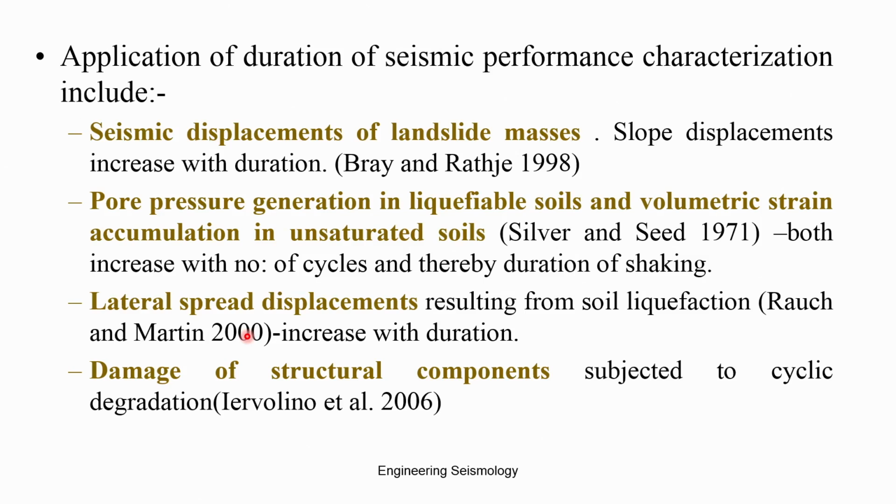Laterally spread displacement results from soil liquefaction. For damage due to lateral spread, or moving of some object from its original position to another position, the number of repeating cycles is very important. Damage of structural components subjected to cyclic degradation is also controlled by this duration. There are many places where the first earthquake will leave only cracks, but subsequent earthquakes or subsequent vibrations can cause damage. There are cases reported in this aspect.